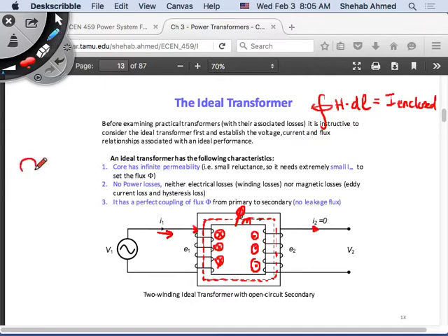So if you have a voltage source with a short circuit across it, regardless of how much voltage you place here, picovolt, nanovolt, whatever voltage, infinite current will flow if the source can provide it. So it's like you don't need any voltage for current to flow. Sort of the same idea here. If I assume that the core is ideal, then I don't need any mutual magnetic flux to be able to create the voltages on both sides. That's sort of what it means. We'll look at the equations that will help you.